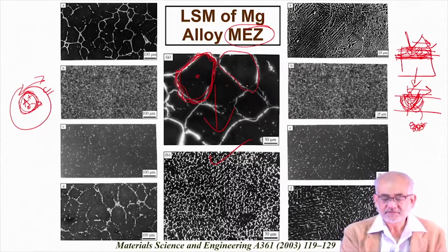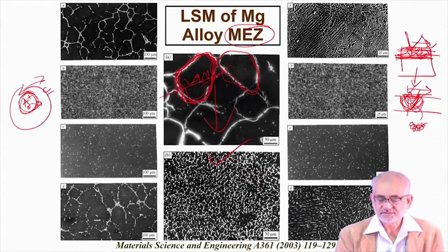Also, this kind of microstructure will mean that these regions will be harder and more wear resistant than the core. So again, during relative motion, these portions will undergo more wear than the grain surfaces. So by surface melting and rapid solidification following the laser surface melting, if we can convert this kind of microstructure into ultrafine microstructure like this, we were able to demonstrate that it gives you twofold benefit.